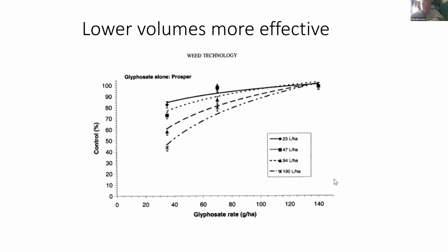And I can assure you, all of you who are listening, pilots, over 90% of all glyphosate applied in South America, especially Argentina, is applied using less than 1 gallon per acre. We have less drift because the product is more concentrated. Pure glyphosate does not evaporate. If we spill it on a loading platform, it will take 2 to 3 hours to dry, and even then it's not completely dry. So it's non-volatile, it's systemic, it does not need small droplets. The best way to reduce drift is to reduce the amount of water.